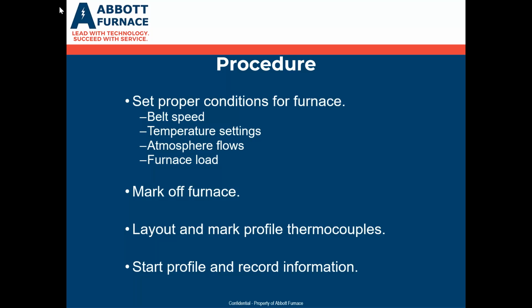And then, once you've got everything strapped on and tied down, you start the belt up again, start the profile recorder, and as it's going through, you just keep an eye on it. And when your tape marks get to the hood, you hit a button and it gives you that vertical line so that you know where you're at as the profile's going.